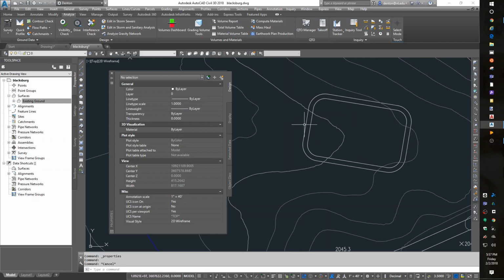What I'm doing is making a ring, both at the same elevation. The outer part needs to tie into the existing ground. So it'll step down to the next contour interval, draw around it, and tie into that contour. These are 5-foot contours on the screen, but it'll do it for each contour down. 5 contours will be down here. 10 contours will be out here somewhere. But anyway, let's see how it looks.